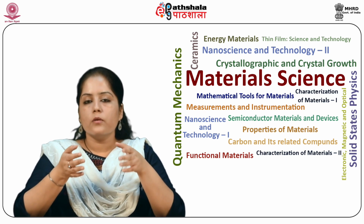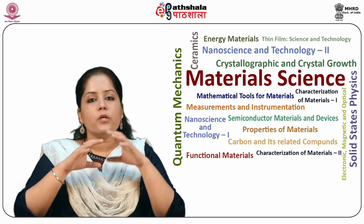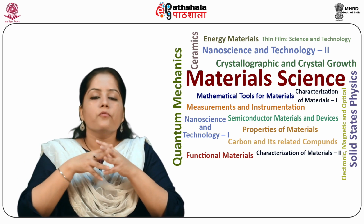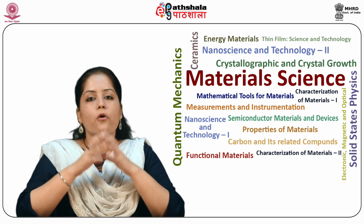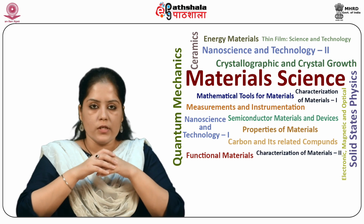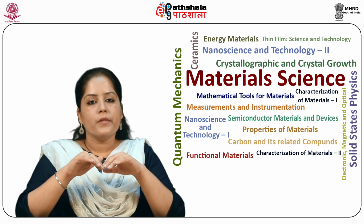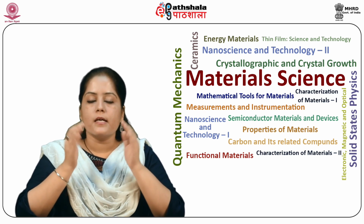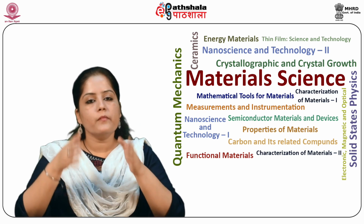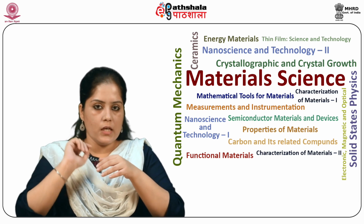Now we find Vd saturation from equation 16 and substitute Vd equal to Vd saturation in equation 10. We can obtain the expression for Id in the saturation region, that is Id saturation. However, when Na is very low and the oxide layer thickness is small, that is C0 is large, then θ is very much less than 1 from equation 17.